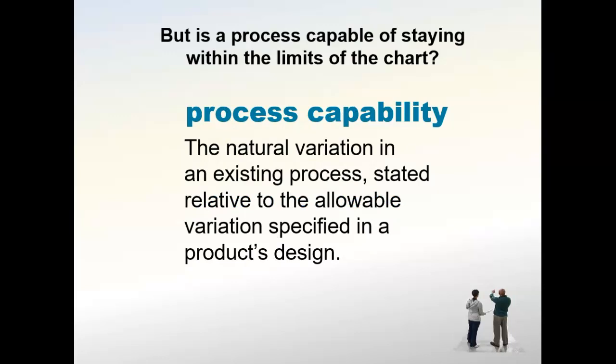Now, designing a good control chart is primarily an issue of locating its limits. Setting these limits is partially an issue of balancing the producer's and the consumer's risk. However, no successful balance will be found if the process itself is not capable of supporting production.